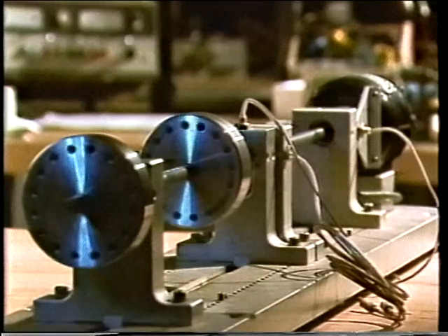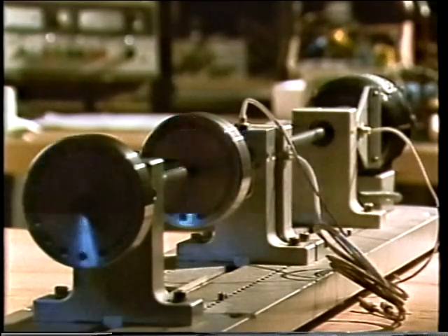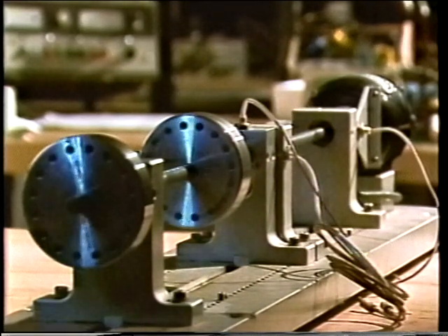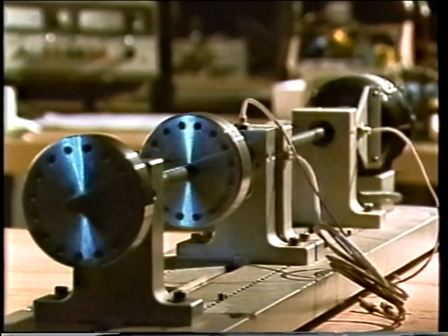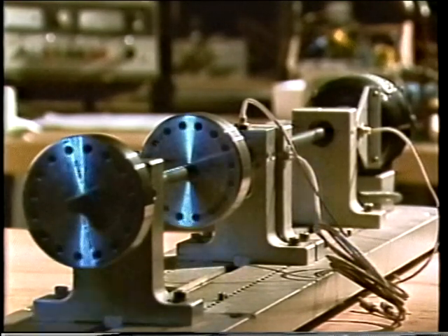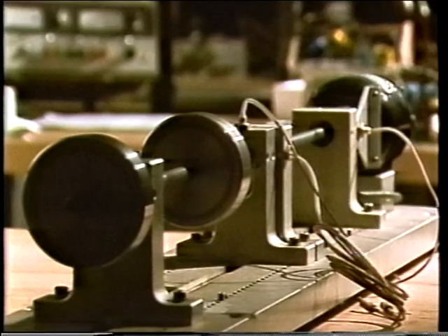One of these marks on the shaft is chosen to compare with a fixed point on the stationary part of the machine. The angle between the chosen mark and the stationary point is called the phase angle. The phase angle is used in conjunction with the amplitude of the vibration to balance the rotating equipment.